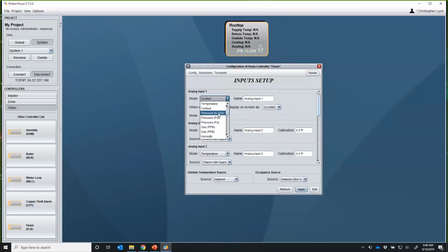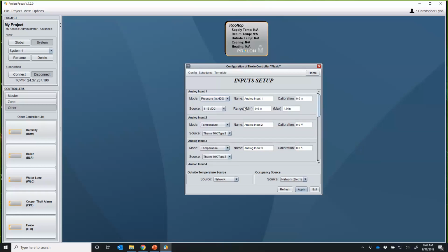Okay, now we start into our linear measurements. So we still have the pressure, inches, water column. Remember, your first number can always be negative if you're using a bidirectional transducer. Still have the whole selection of signals. So let's just run down the inputs real quick.